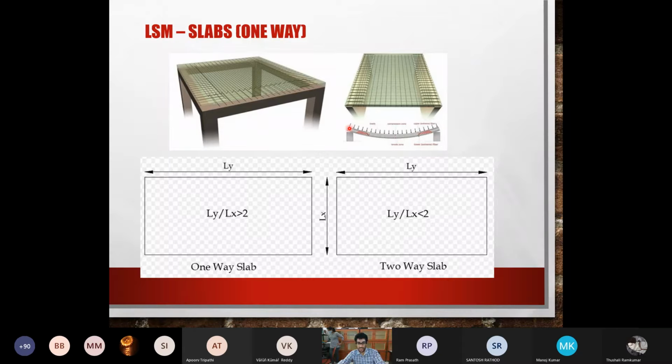Okay, this is how the slab is going to bend, meaning whether I am at this part, this part, or this part, wherever I am along this direction, if I cut a section, this is how the deformation of the slab will look. So whether you are at this end of the slab, at the middle, or at the other end, if you cut a section and look at the deflected shape, it will be identical. Okay, so this is one case.